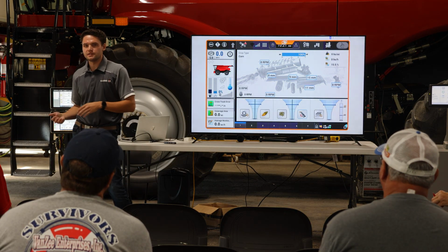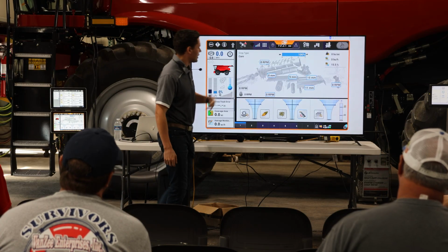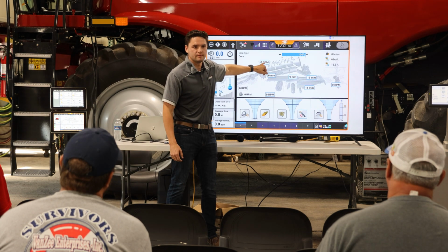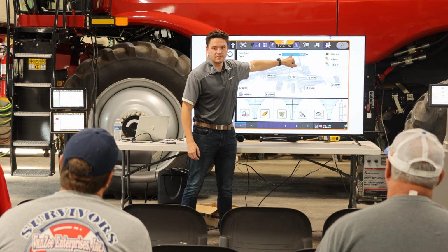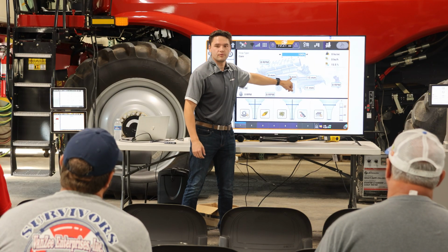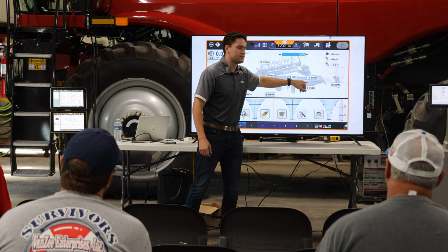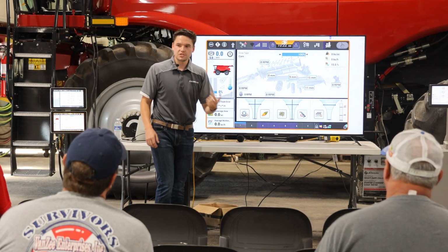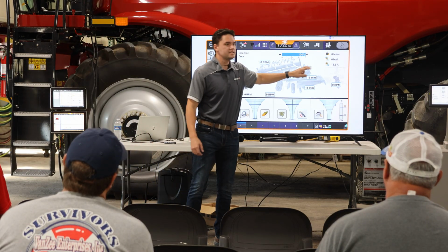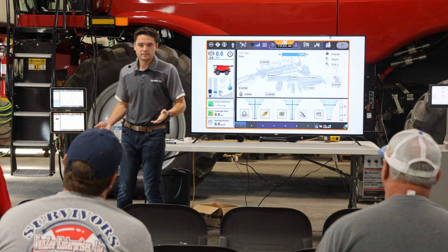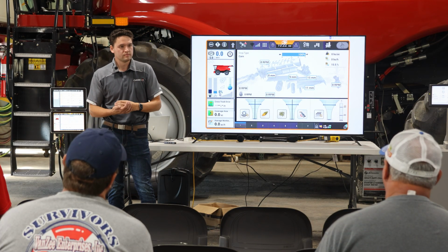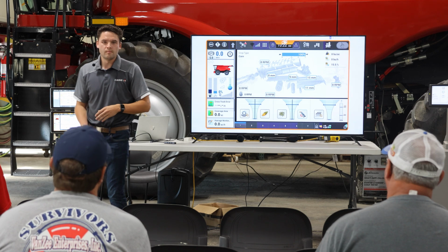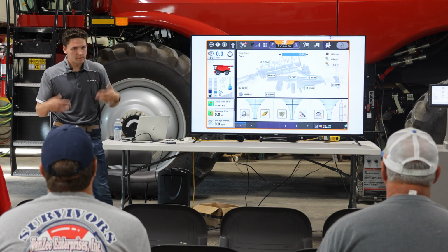That's not actually what happens with this. The reality is, as automation is running and we have automation active, it's going through and saying, is my rotor spinning at the speed that I think it should be? Are my cage vanes in the position I think they should be in? Is my pre-sieve at the clearance I think it should be? My upper sieve, and my lower sieve, and so on, and all the features that it controls. So when it does its checks and gets to that upper sieve and sees that it's at 18 millimeters, what does it do? It says, that's not where I left you. And it closes it down to the 15 millimeters, which caused what? Sieve loss.